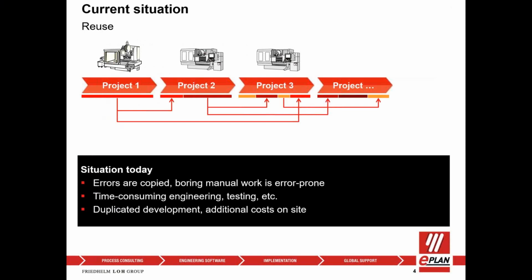A relay is a relay, a PLC card is a PLC card, but the data inside those elements changes. If it's a relay from a particular company, or a different relay from an additional company, amperage, voltage and technical data will change. Visual data, or what we see on print, does not really change that much. A distribution page is a distribution page, and so on and so forth. So that's what we're talking about here, the reusability.